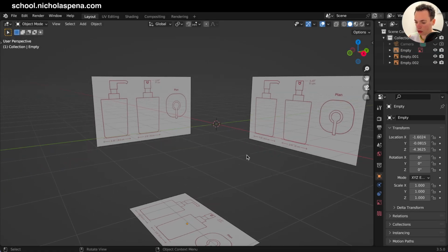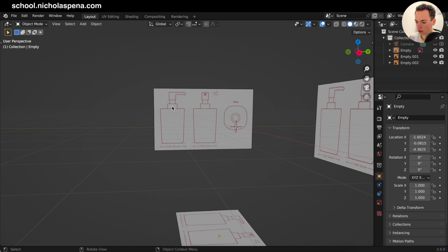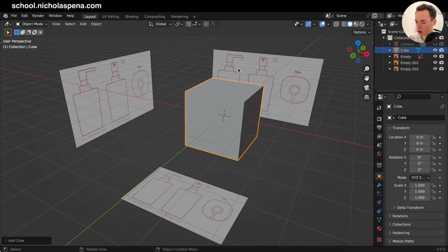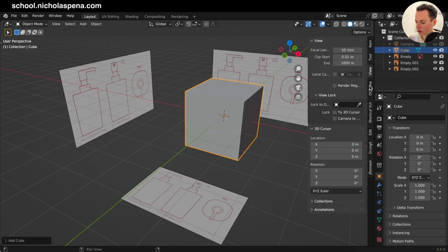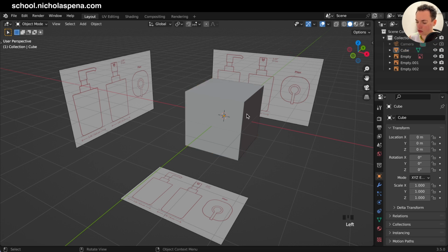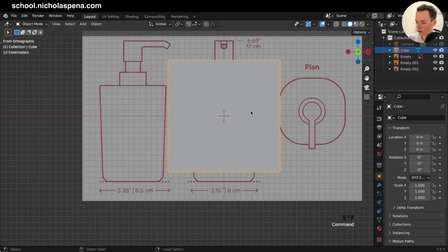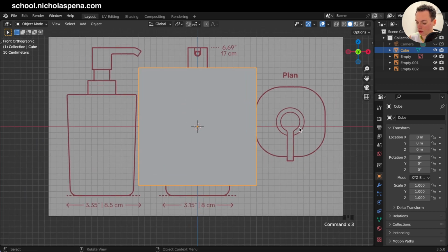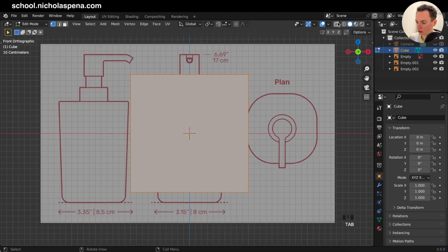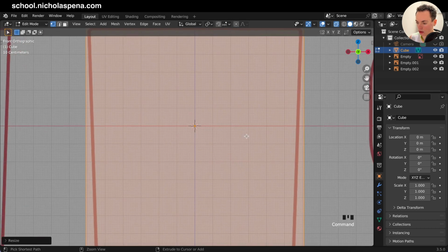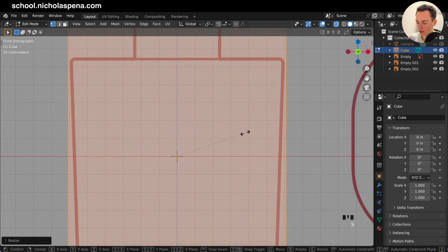So first we are going to make this part, extrude, and then make the top part here. Shift A, mesh, cube. And I'm going to put the hotkeys so you can see here. So we have this, go on numpad 1, go on this view, and then we are going to check the other views. So we get the cube, tab, edit mode. We can also go in X-ray here. S, X, this smaller. So here, the size of this.